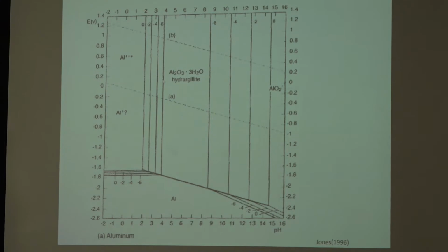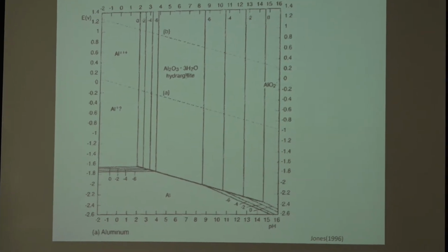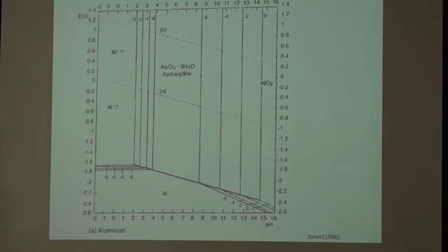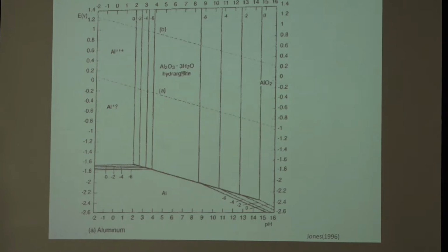So aluminum here in the zone B, we have the stable oxide of aluminum, the alumina, that will essentially resist the penetration of more oxygen, and it remains stable on the surface. So if you scratch aluminum, a lot of times it will remake that layer very quickly, and you don't have too much trouble. Now, there are exceptions. If you put aluminum in concrete, now all of a sudden you can see you're becoming in another phase of aluminum.